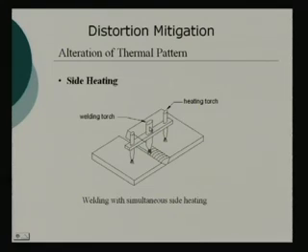So, what is basically happening here is that it is mitigating the effect of the central torch. The heat flow that was taking place, whatever expansion it was trying to do, I am simultaneously heating on the side. So, it will try to expand in the other direction.